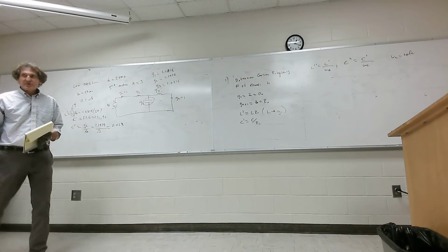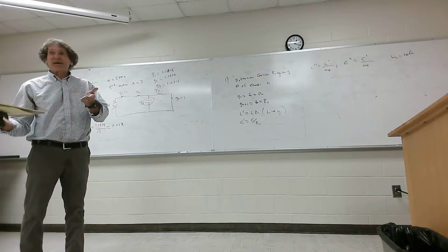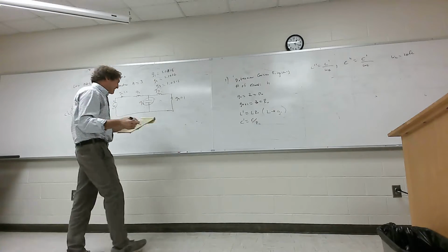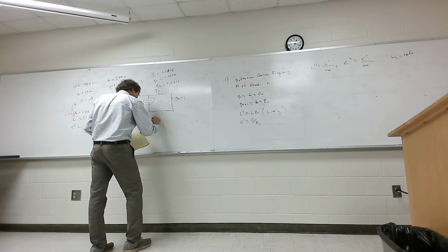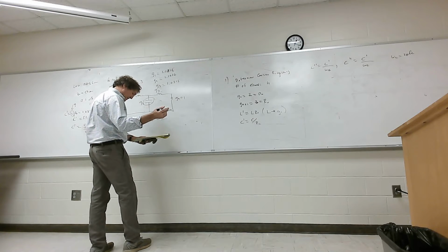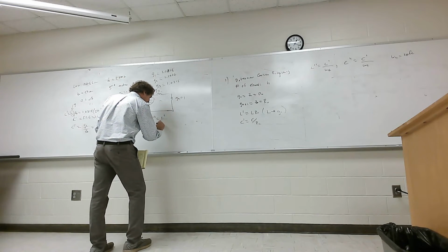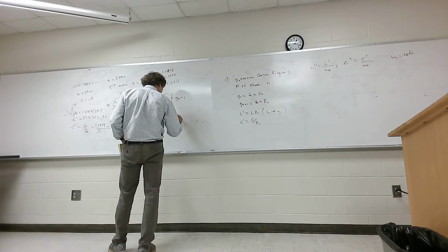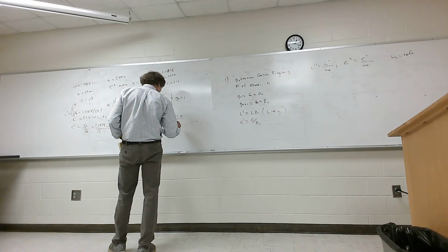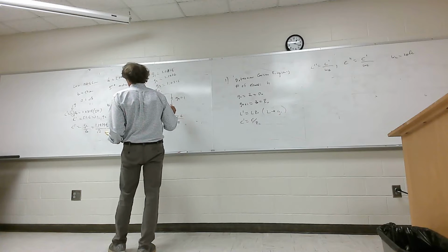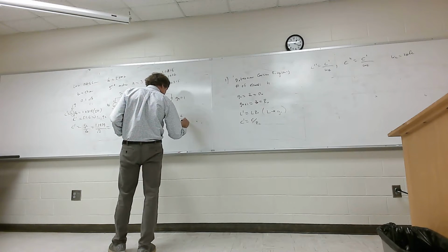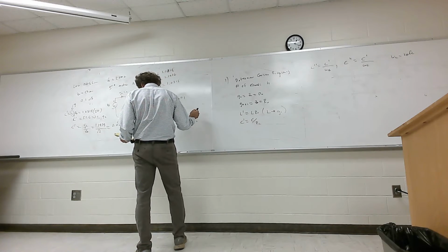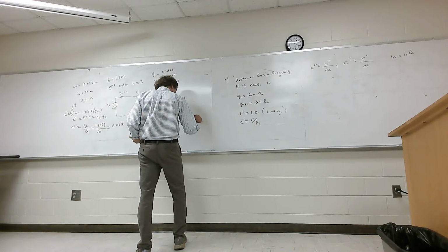Now after that, what we have to do is get the actual values. If you don't like it, I understand, but this is the way it's done. I would prefer a much more in-depth treatment of this, but this is how it's done. Anyway, you get L double prime, equal to L prime over 2 pi times the cutoff frequency, FC. L prime is 51.6 divided by 2 pi, and this is at 2 gigahertz, so times 2 times 10 to the 9th, and that is equal to 4.1 nanohenries.